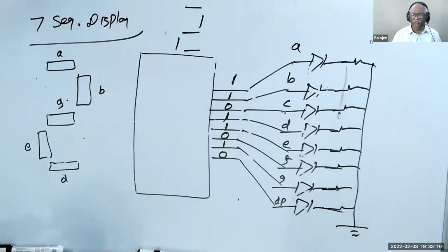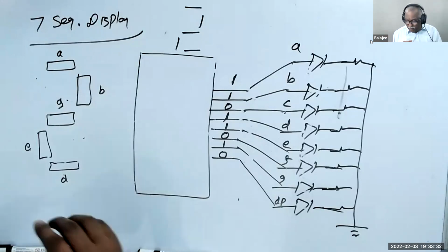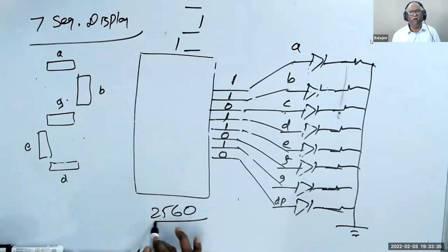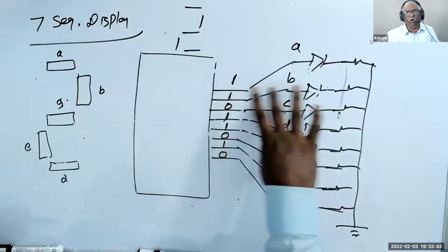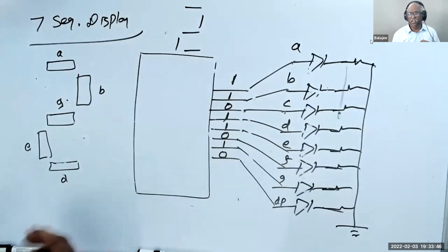Yes, if you buy an IC with only 8 pins, you will get only 1 port. If you buy an IC with 100 pins, you will have more ports. You can buy an IC with a different number of pins. The same IC is available with different pins. I'll show you later when I refer to the data sheet. So I can buy the same ATmega2560 IC with fewer pins or more pins. Internally the CPU will not vary, everything will be the same. Only the number of ports outside will vary, depending on your cost. If you pay more, you will get more ports. If you pay less, you get fewer ports. That's it.